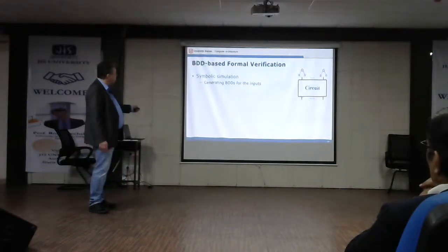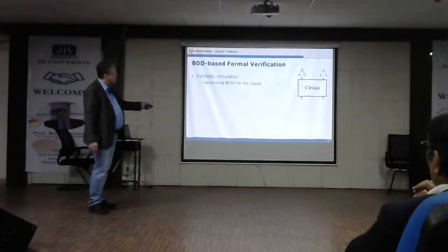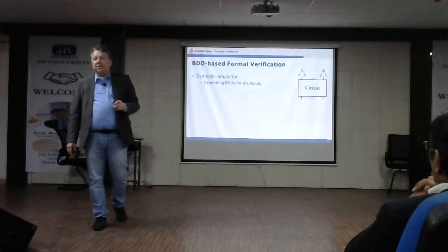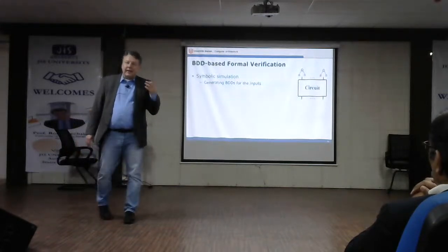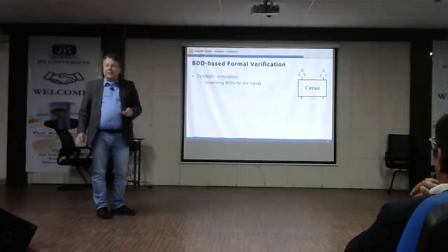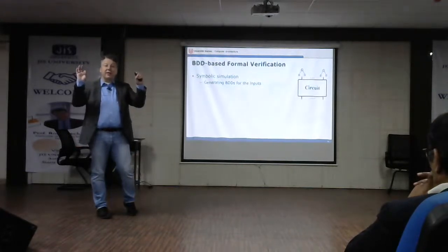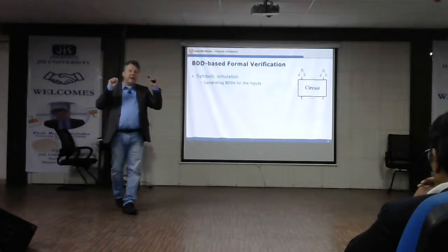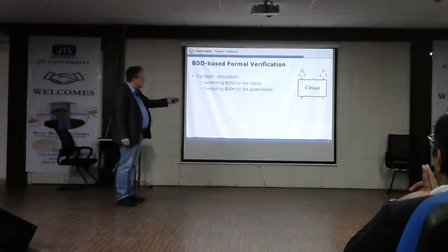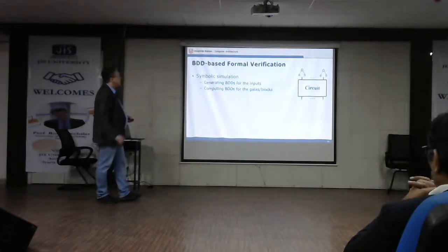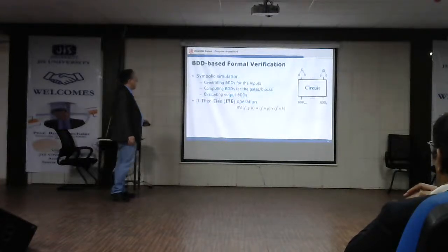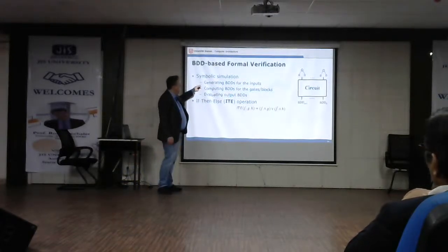And what you do there is that you generate BDDs for the inputs. And now the difference to the simulation that you are using is that here you are not applying zeros and ones, discrete values, but symbolic values. You're calculating with the symbolic values. You propagate these BDDs, these symbolic values, through the circuit, and then you evaluate it towards the outputs. And you do this kind of internal operation for these blocks.